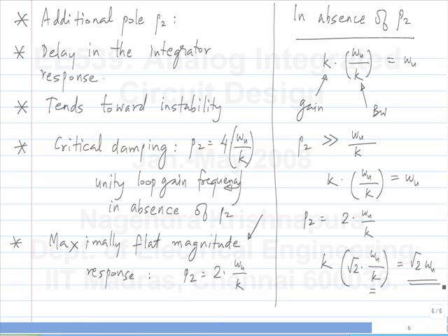So, the gain times bandwidth will not be exactly constant. In fact, I would suggest that you look up some very high speed op amp, it will say something like, if you apply it in unity gain, the bandwidth will be 250 megahertz, okay. And if you make an amplifier of gain 10, what should be the bandwidth?